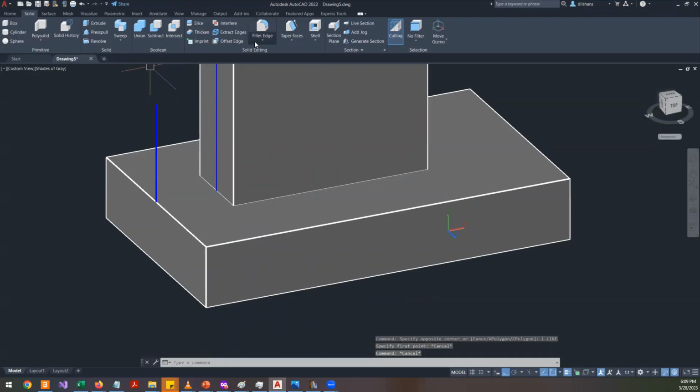Do I have the copy edge command? Okay, I will simply draw a line. I will teach you that command later. So I'm going to draw a line with 5 millimeter height, and then I'm going to use offset. For the distance, I will use cal because I want to access the calculator. The distance is 150 minus 126 divided by 2. So that is the offset distance. Enter.